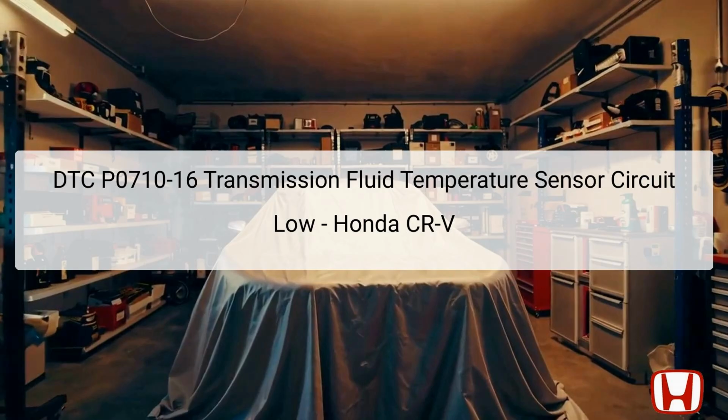performance and overall drivability. The location of the transmission fluid temperature sensor is integrated within the solenoid wire harness A, directly attached to the TCM. Thus, any faults in the sensor or its connections can lead to incorrect data being sent to the TCM, which can affect transmission operation. When troubleshooting DTC P0710-16, it's essential to check both the sensor and the wiring to ensure proper function and connectivity.